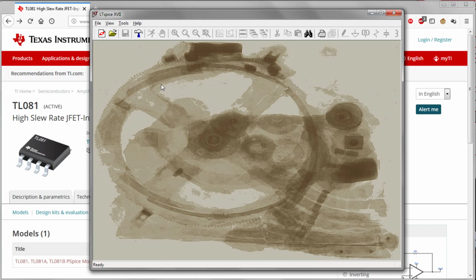And well, if you're watching this, you probably already know that LTSpice does not include a very wide range of commonly used components. For example, the 741 op amp, which is very popular, is not included in the default library when you download the simulator. So at some point you will find yourself needing to add a component to the library.